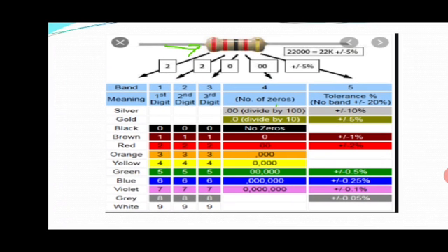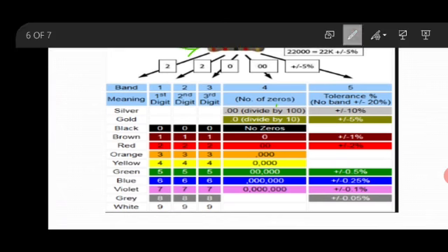Next, go to the next circle on the resistor. Which color can you see? Again it's red. You mark it as 2, so just write the value 22. The next circle is black. What is the value of black here? 0. So 220. Now you come to the column in this fashion. I completed the 1st, 2nd and 3rd circles. The fourth circle indicates the number of zeros.